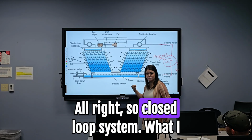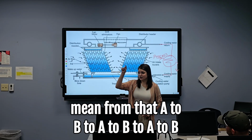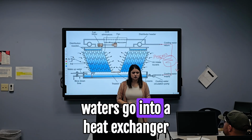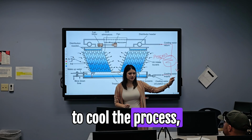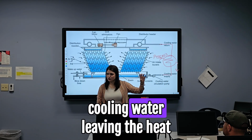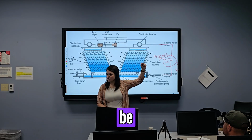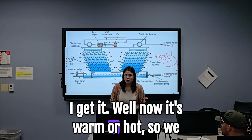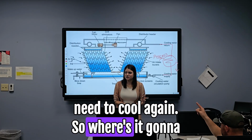All right, so closed loop system, what I mean by that is A to B to A to B to A to B to A to B. Leaving our cooling tower, the cooling water is going to a heat exchanger to cool the process, which we know to cool something, we have to absorb heat, right? So the cooling water leaving the heat exchanger is going to be warmer because it's absorbing the heat from the process. Well, now it's warm or hot, so we need to cool it again. So where's it going to go?